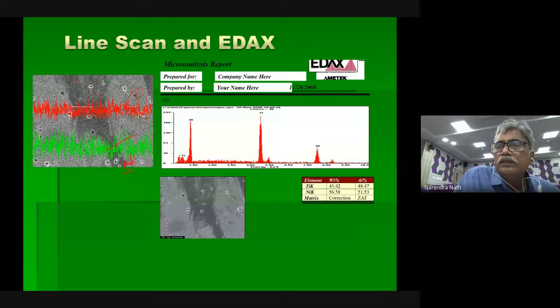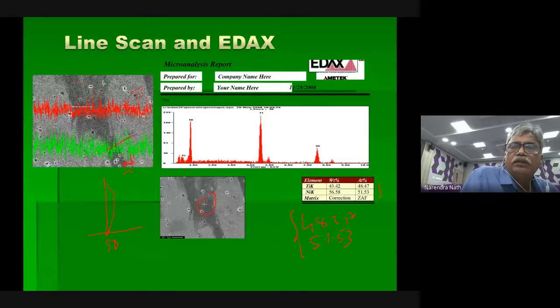And we checked at this point what element is present here. You see here, atomic percentage 48.47 and 51.53. You remember our phase diagram, the triangle point coming like this at 50. So that is well within that. By proving all these things, it is equiatomic titanium nickel with very good transformation and shape memory effect.